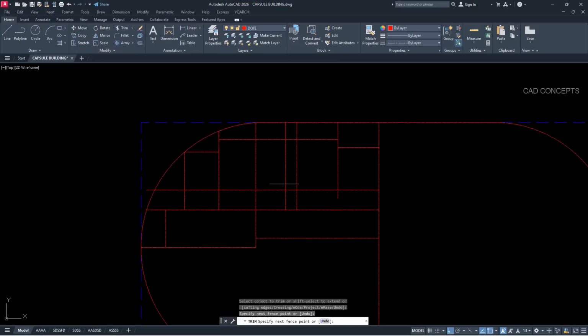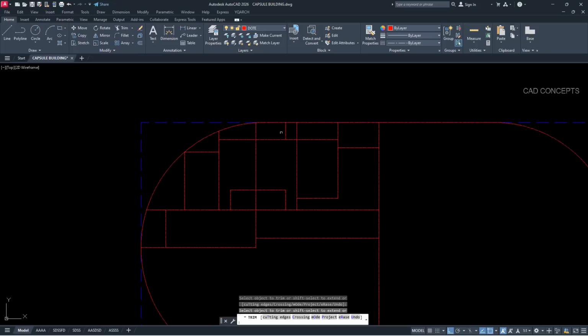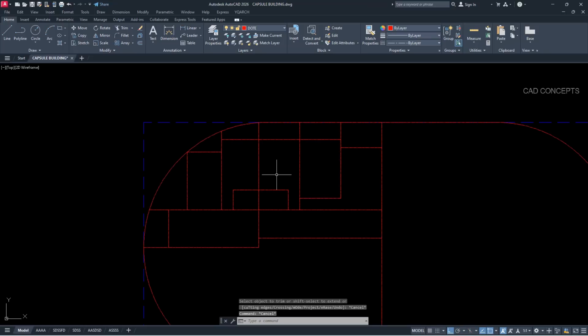100 centimeter, and trim this area. And here also, same distance here, and trim this part. Okay, this is our attached bathroom for the bedroom. Okay, 360 by 240 we are getting, wider space. Okay, minimum you can keep 180 by 240. So we are getting good enough. Same, mirror this area.